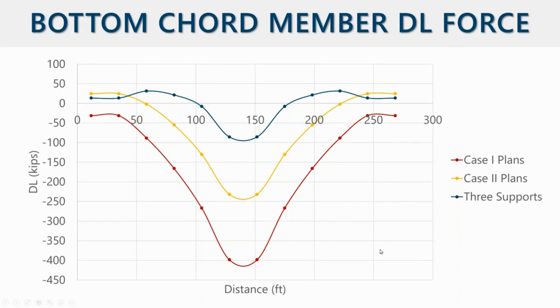So the main challenge is here. First of all, for live load, we have 3 supports. No problem, no question on that. For dead load, we only have 1 support. And unfortunately, in BrR, you cannot really switch between these. You cannot set different boundary conditions, different supports in the model for the dead load and the live load. Another challenge is how we can consider those 2 dead load cases.